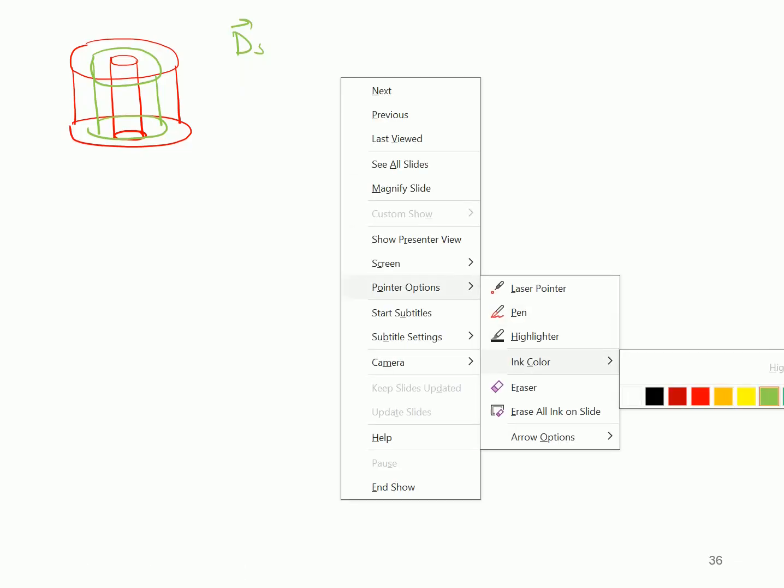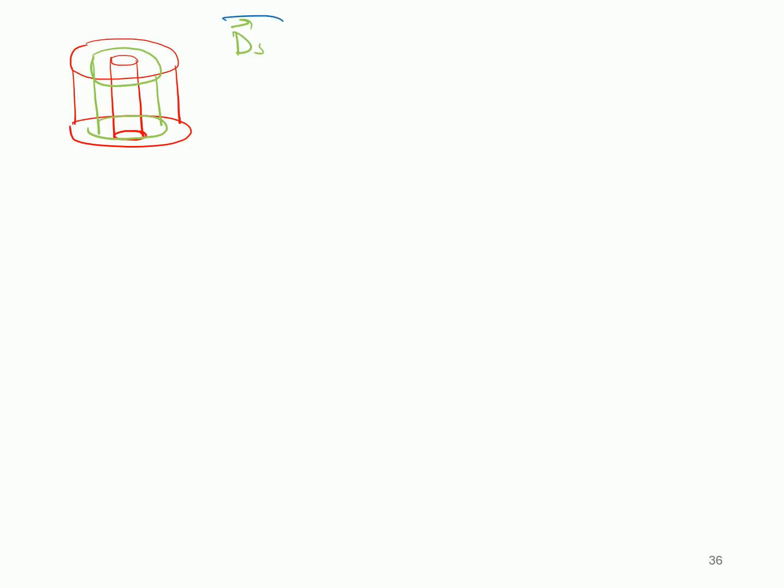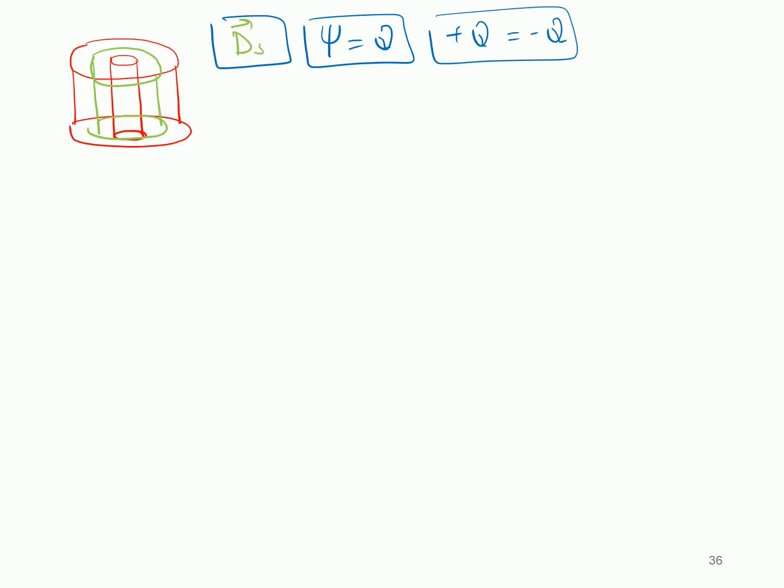We also want to find that out, because as per Gauss's law, or Faraday's experiment, we know that the total flux passing is equal to the total charge, or that whatever the charge inside, it is going to appear at the outer surface with a negative charge. So if plus Q was the charge on the inner conductor, we found that the same charge should exist on the inside of the Gaussian surface. And if this charge appears at the Gaussian surface, then the outer conductor should have the same charge but with the negative sign. So let us see the relationship now.